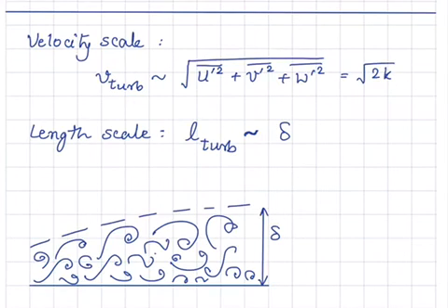So this gives us an estimate: if you know the turbulent boundary layer thickness, you can make an estimate of L turbulent, the length scale of turbulence, put it back into eddy viscosity, and then that gives you Reynolds stresses, and you can compute the mean velocity profile. But then how would you calculate the mean velocity profile, or the boundary layer thickness delta, which actually comes from the mean velocity profile, before calculating the mean velocity profile? So it's not a very easy thing to do. You have to make an approximation, try it out, and then maybe correct it if you wish.